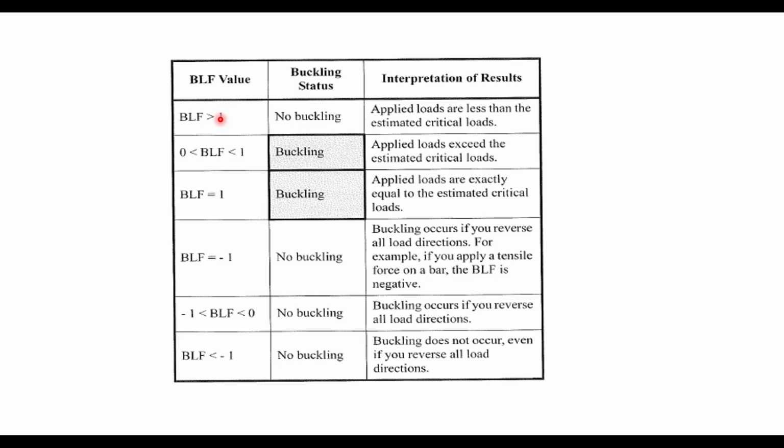Now, a very important thing is you should not take only 1 as a reference. Sometimes, as per the factor of safety, some components will have a buckling load criterion of 4, 4.5, 6, 2.5 or 3.2, depending on the case. So we need to consider that. You need to ask what the buckling load factor standard is for this model. If they say it is 1, consider that. If they say some other value, please take that into account.